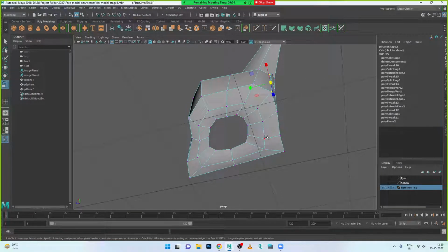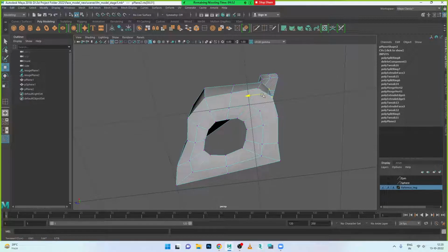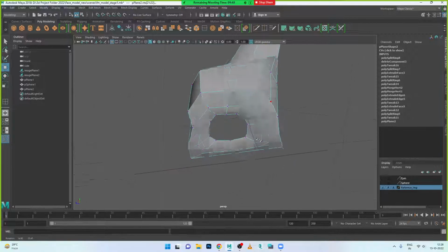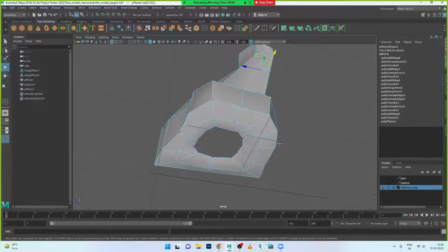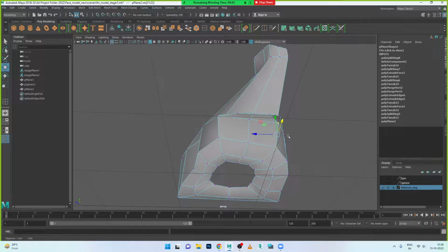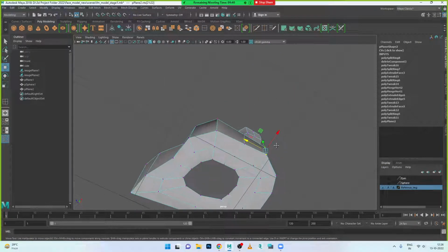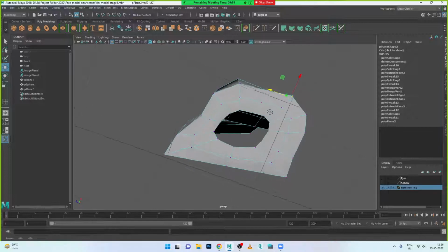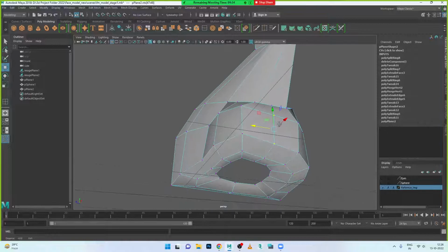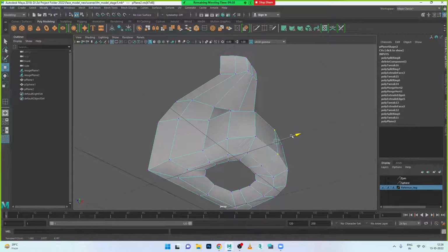Select these two portions and try to send a little back side on this one now, for applying the smoothness on this one now. Set these two. Yes, no vertexes should be selected on the top. See this very carefully. Move from front, so it should be a little round on this one now. So move and select these two vertexes and see no other vertexes selected. Move it a little outside now.